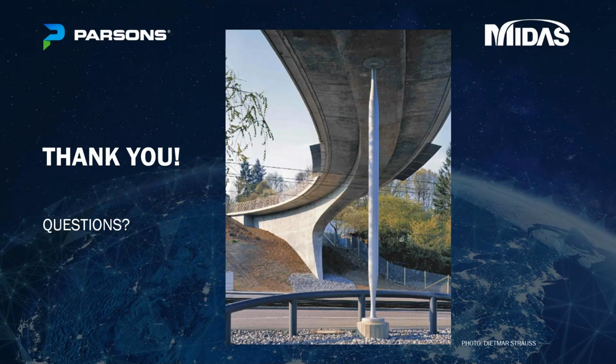Okay. Our next question says, how does the fill behind the abutment contribute to the modeling? That's a good question. That depends on how you compact the fill behind the abutment, when it's compacted, and how it behaves. But typically you consider this with a spring. The problem with a passive soil pressure is that it's a nonlinear spring. So the more you push, the more is the resistance. So it's not a linear one.